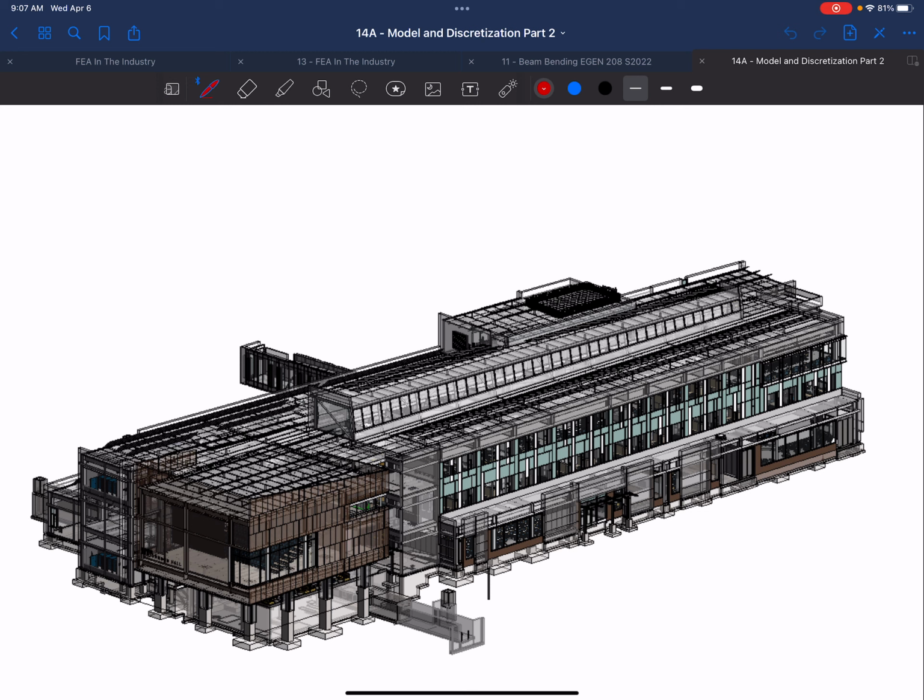When they create a model from a Revit model, they look at the analytical model in Revit and not this model that we're looking at, the three-dimensional one. So it makes sense to go in here and ask, where is my analytical model? There are ways that you can align it to the center line of beams versus the top flange of beams and things like that.